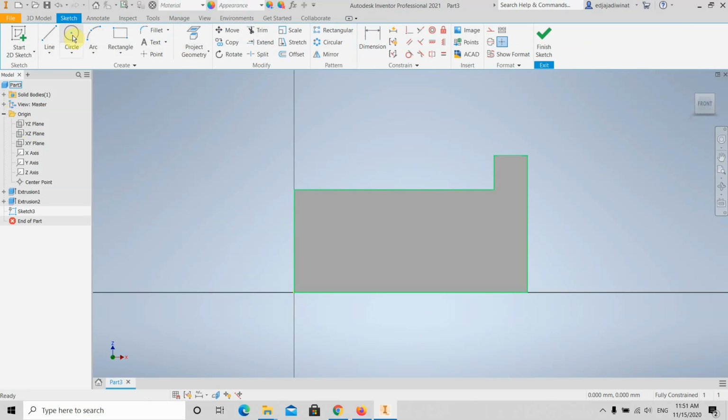So what I'm going to do, I will draw a circle. Okay, I will snap the center of the circle on this line. Make sure it snaps to a line. So it's only a red line with an arrow. You see the symbol near my cursor, a line and an arrow. If you snap here, when this snap is on, it can still move along this line. Okay. If you snap when you see a point, it will not be able to move, so you cannot adjust it anymore. It's fixed on that point. Okay, you need to pay attention to these details.